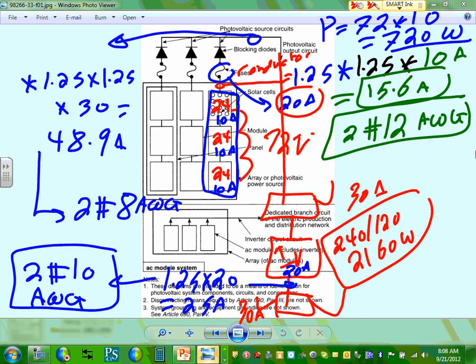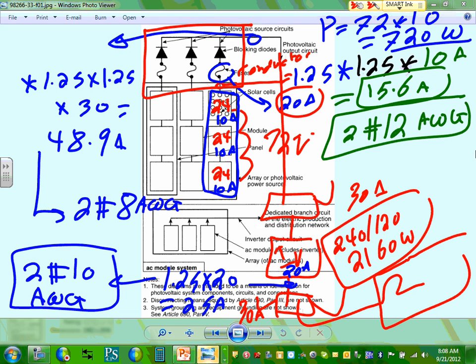All you need to do now, Aaron, my friend, is get your conduits, EMT conduits or PVC, pull the conductors that I told you about, and put in a junction box. There will be a J box here. All of this will be in a combiner. They call it a combiner, and off we go. And from this side, where do you go? You tie it to your panel.